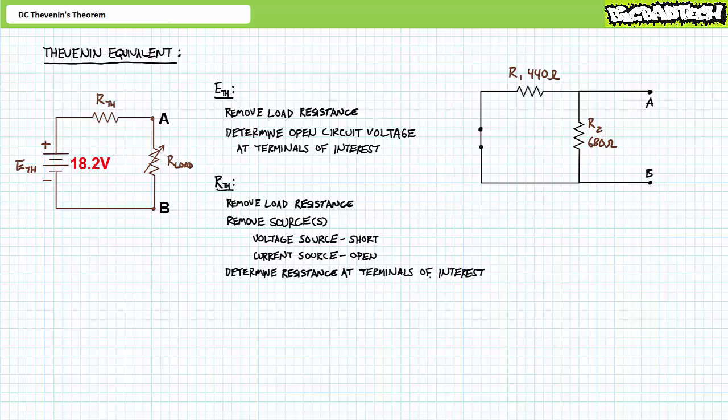Finally, one reads the resistance of the modified circuit at the terminals of interest. If you want to, you can draw a little ohm meter on the terminals of interest, reminding you that perspective has shifted. The removal of the source and perspective shift changes the game, and a lot of people unnecessarily freak out about this. Chill out, relax, visualize the circuit at the nodal level and from the perspective of flowing current.